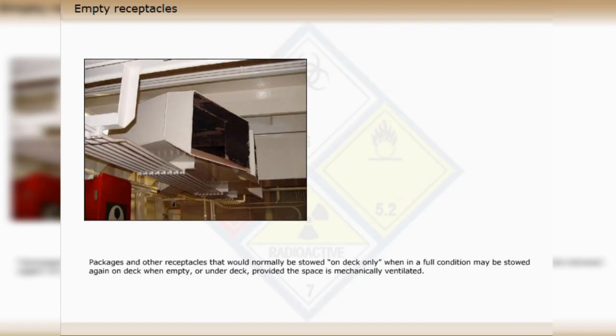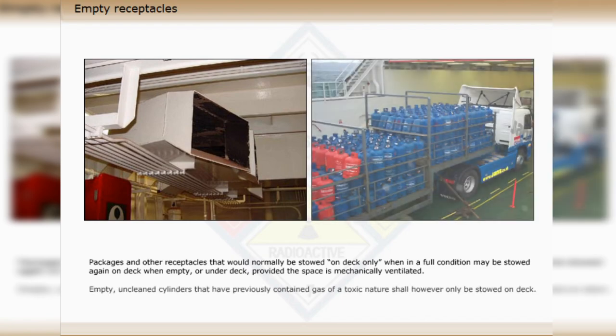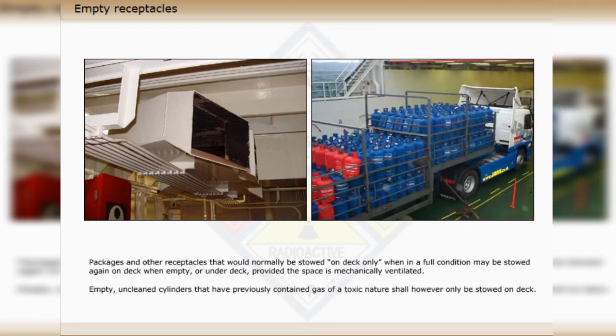Packages and other receptacles that would normally be stowed on deck only when in a full condition may be stowed again on deck when empty or under deck, provided the space is mechanically ventilated. Empty, unclean cylinders that have previously contained gas of a toxic nature shall, however, only be stowed on deck.